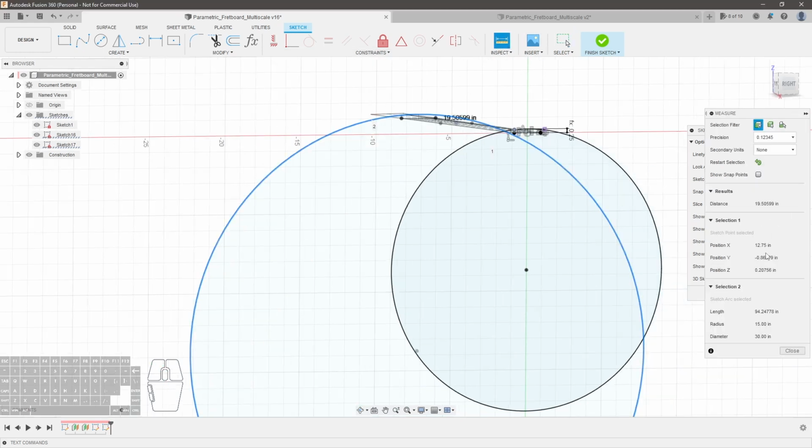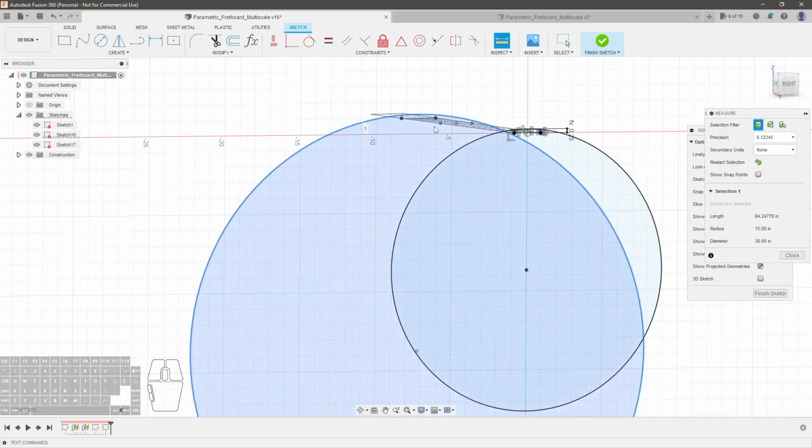So that one was a 15-inch radius. And this one is an 8.93639-inch radius. And so if you're doing this with a CNC, that's totally fine, right? Your CNC can cut that. If you're trying to sand this manually, that becomes a bit of a problem.